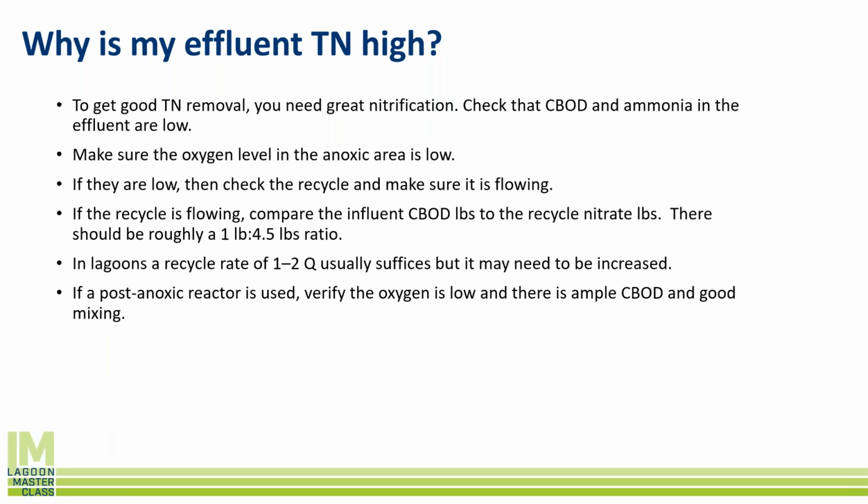So it has some really good benefits. And it's easy because there's no chemical dosage. If our permit is between, say, 8 and 10 total nitrogen, recycling works really well. So to get that good TN removal, we first have to get the nitrification down to about 1. Then we need to get that nitrate back into a mixture with that CBOD by recycling it.